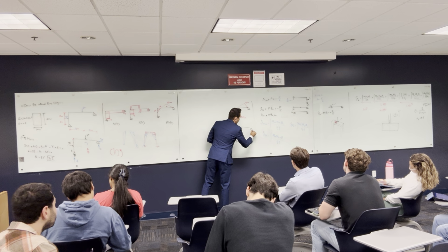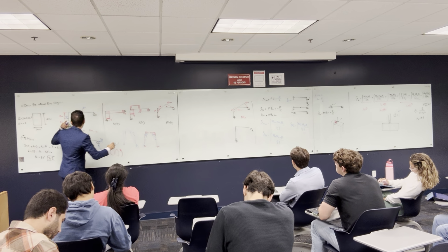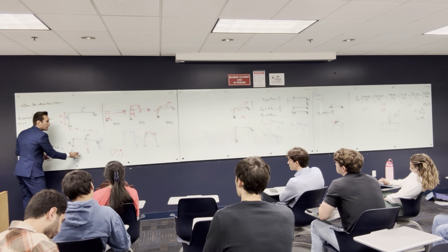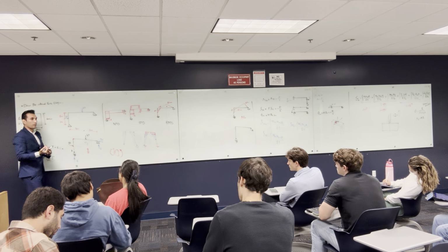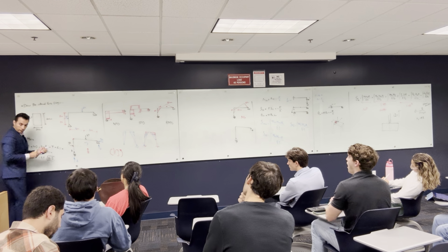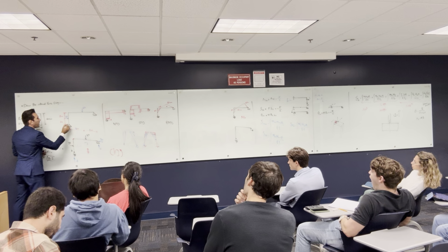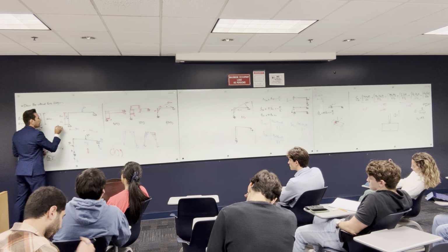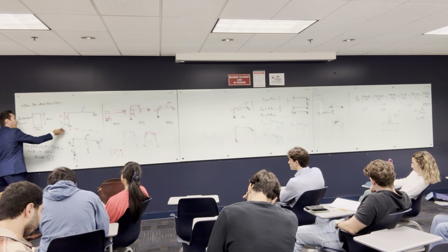You will draw the same system after taking the original load out. I'm going to take the 3 out and the 6 out, and keep the main system, but I'm going to put a unit load at the removed redundant. Where's my redundant? What did I remove? Look, this is roller, this is hinge. What I removed is the X reaction here. Let's call it X. That's what I want to find the value of.